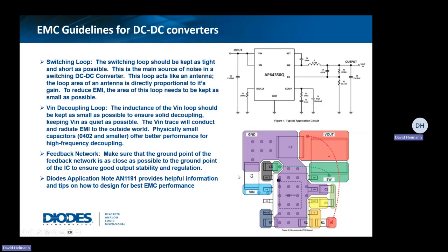The other thing I'll note is that on your input caps, you're typically using fairly high value capacitors, which means the case sizes are generally going to be larger. When you're looking at multi-layer ceramic capacitors for bypass, the smaller the physical case size of the capacitor, the better performance it's going to have for high frequency decoupling.